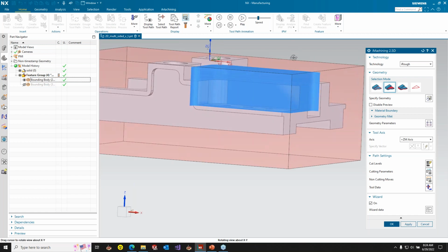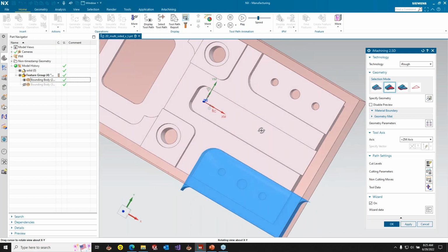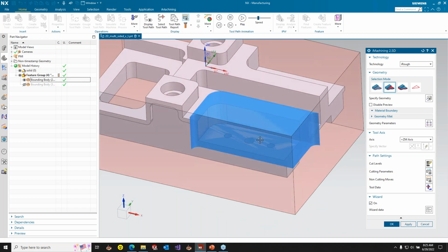So basically what you get in the feature recognition code is we find the 3D region with the levels extended to the stock. If there was a fixture in the way, it automatically protects against the fixture. If you have a holder, it automatically protects the holder against the stock, plus even also the fixture. So all of this stuff gets automatically built and protected, and it's pretty much as simple as picking a face.